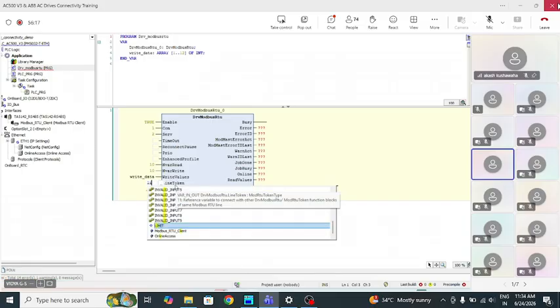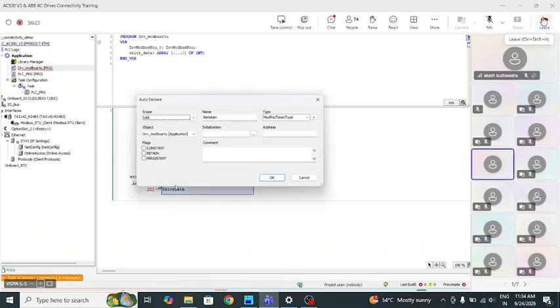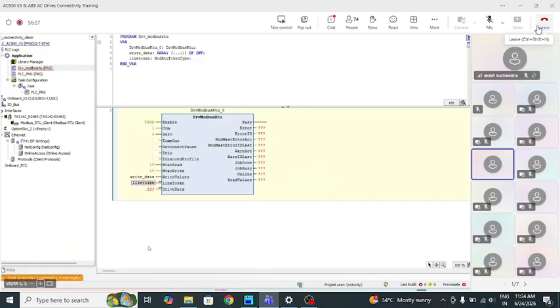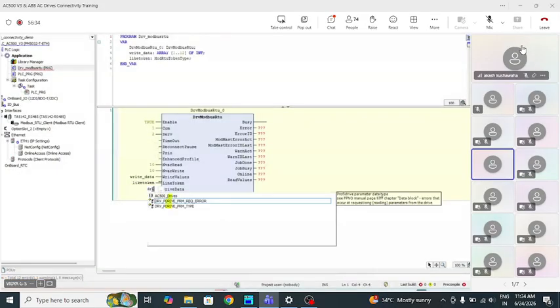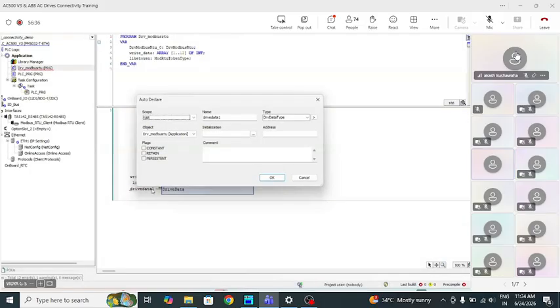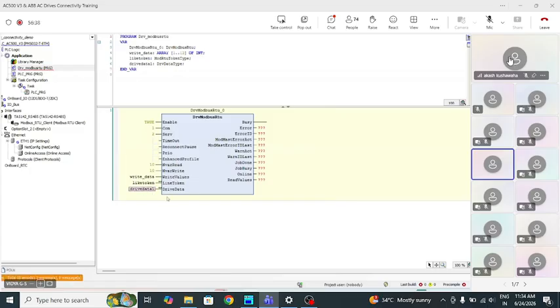This is important if you are using multiple devices connected serially, where you need to link this line token of each device, then only communication will work. Then this drive data: we need to use this when you're linking the blocks of one particular drive.